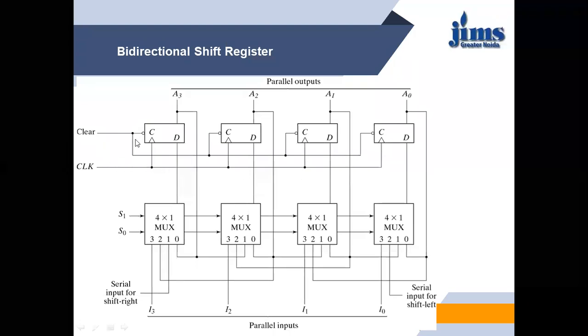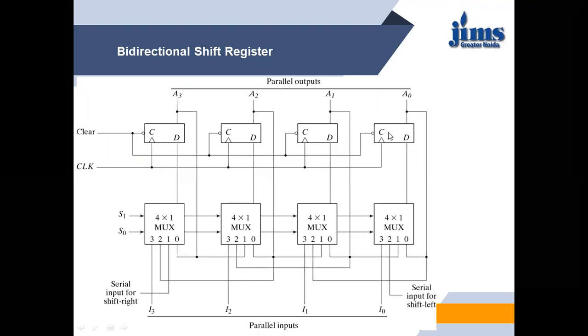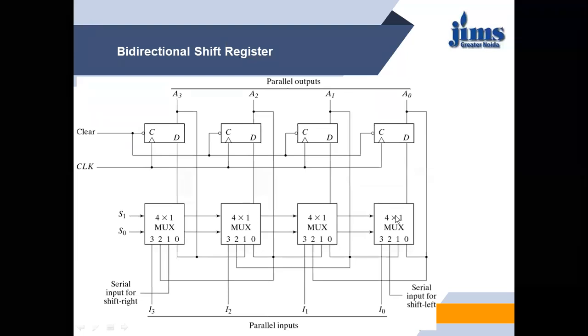We have used a clear pin, so that the initial data is cleared in the flip-flops, and we have used 4 muxes. All the select lines of the muxes are common, that is S0 and S1. These are the select lines. And now we come to the connections.